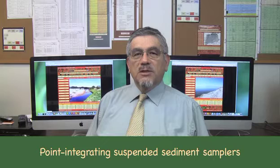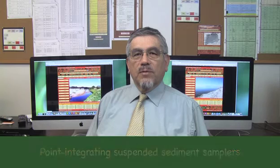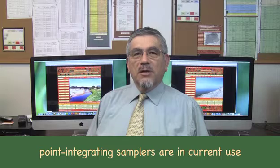Point integrating suspended sediment samplers measure a sample at any point in the stream vertical. These samplers can also be used to take a depth integrated sample over a range of depths. Point integrating samplers are used to collect suspended sediment samples in streams that are too deep to be appropriately sampled with a depth integrating sampler. The US P61A1, US P63, and US P72 point integrating samplers are in current use.